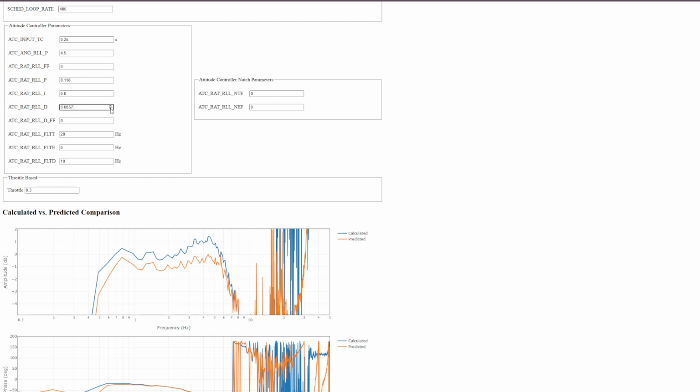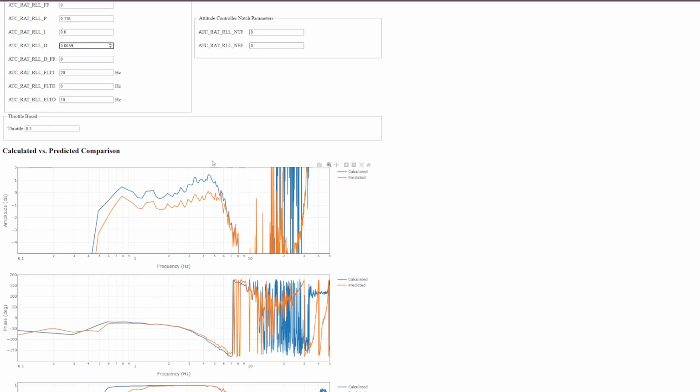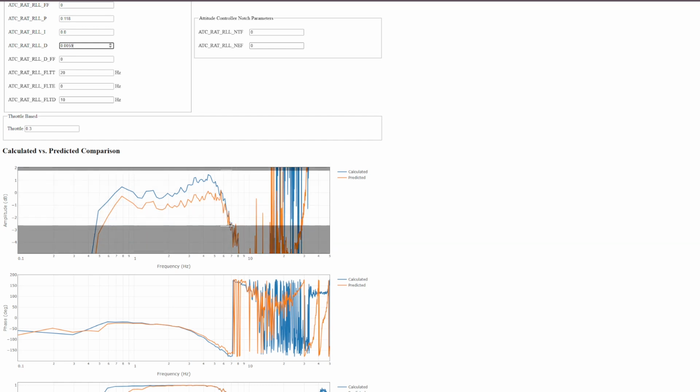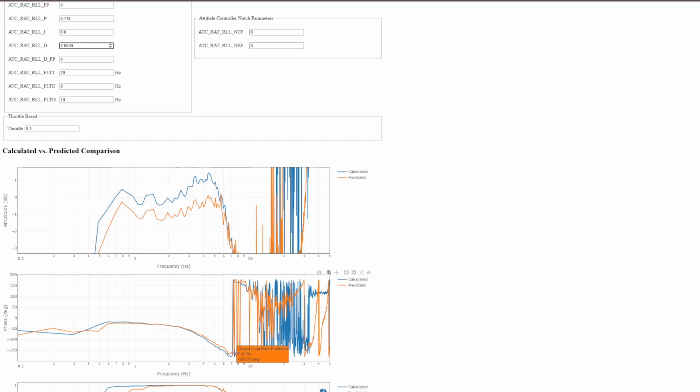And you can see now as we get up here, we start to get higher oscillation, like we're actually getting these higher frequencies. The outputs are becoming larger than what we're asking for. Now the key thing we want to do here is we also want to look at where the output is 180 degrees out of phase to what we're commanding. So basically, when you're rolling left, right, left, it's going right, left, right. It's going in the opposite direction in perfect time with your commanded inputs.